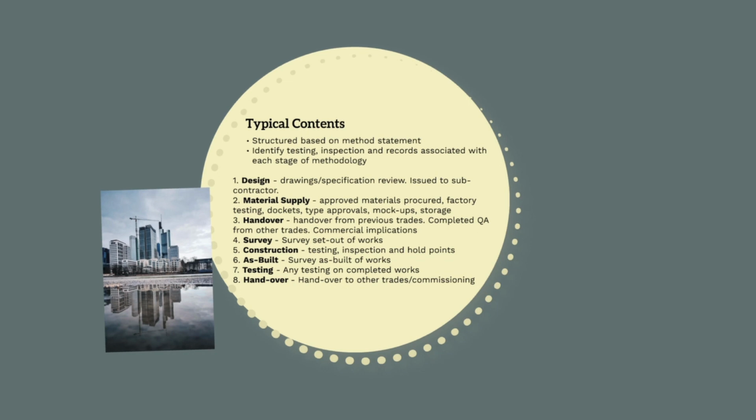When works are complete, there will be checks to make sure that any as-built documentation has been collected, such as survey pickup of conduits. For example, when constructing piles, survey may record top of piles so that this can be provided to the structural steel fabricators. Additionally, any testing to ensure that works are being completed correctly will be conducted, followed by a handover to other trades or commissioning. This is the general methodology used to manage works, and will change slightly depending on the works being performed. For example, for electrical works, you likely won't need as much survey input as for civil works, but electrical works may require more checks that the correct materials are being used.